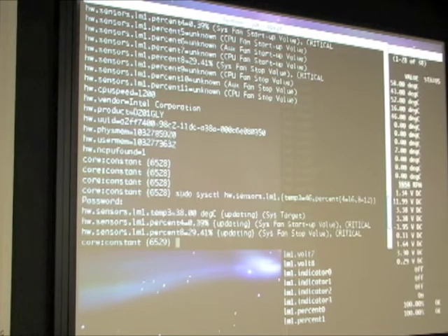So you can see after I issue this command, I get the result of the current readings. And you should also notice here that soon the speed is going to be changing. So the %0 sensor indicates the current value that is being supplied to the fan. And you can see that it goes down. And soon it will reach low enough that the speed is going to be reduced. It reaches 11%, and then the speed of the fan is reduced from 1500 RPM to 1100 RPM.